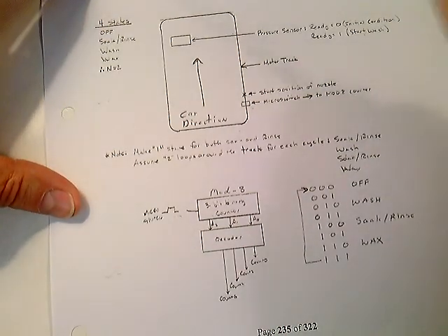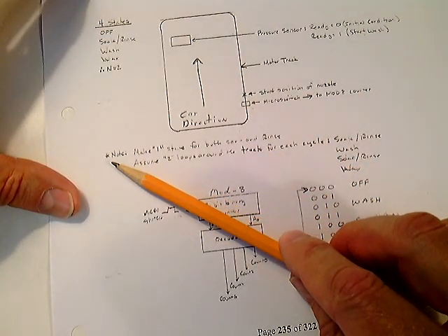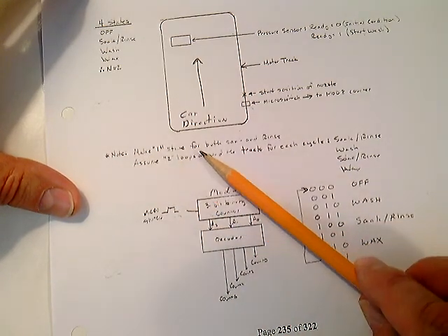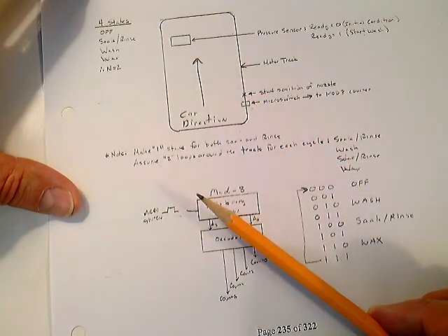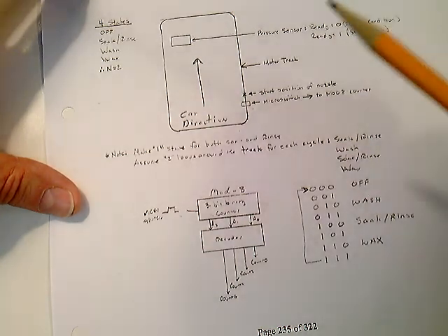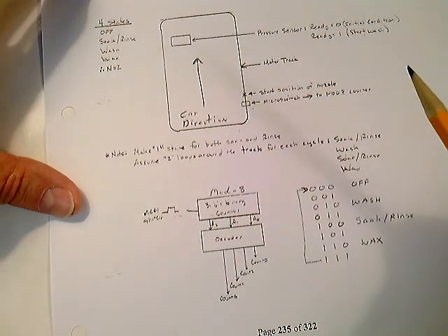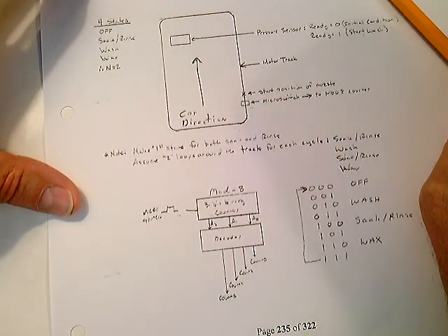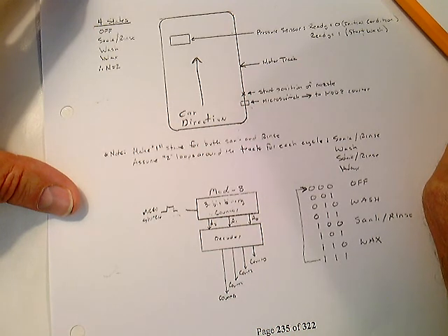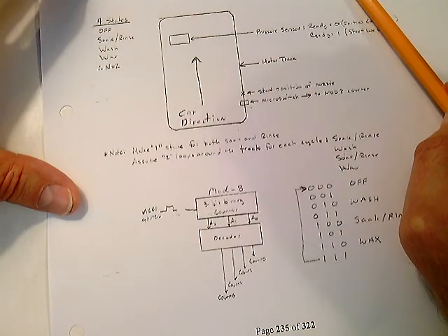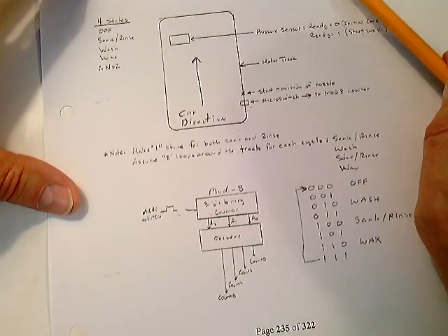So, note here, we're going to use state 1 for both the soak and a rinse to simplify this. So when you're in state 1, we'll use it as a rinse, and we'll use it as a pre-soak. And we're not going to include soap in the pre-soak. So basically our outputs are going to be turn the motor on, turn on the high pressure pump, and you either have the water valve opened, the soap valve opened, or the wax valve opened. So there's only 5 different possibilities.